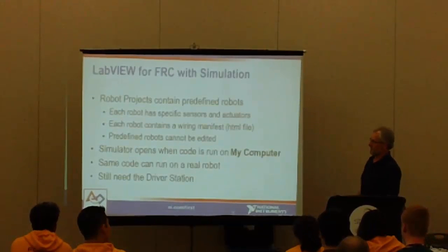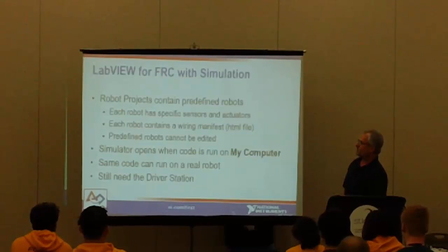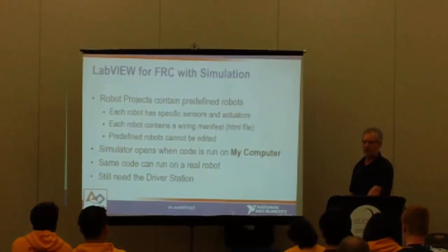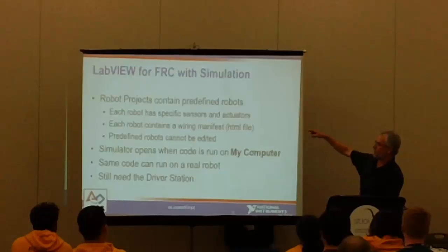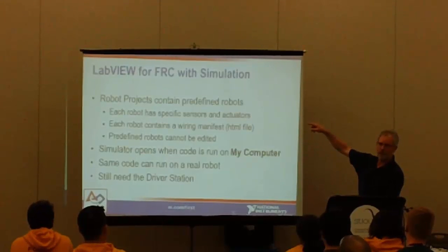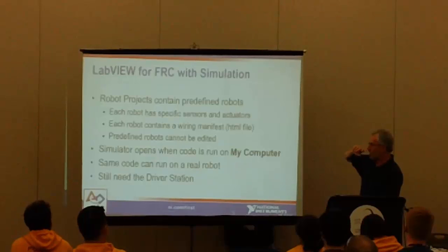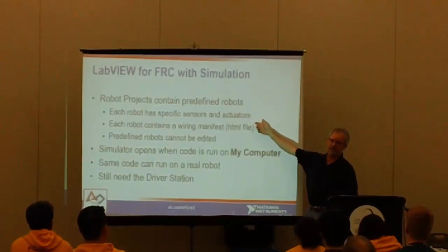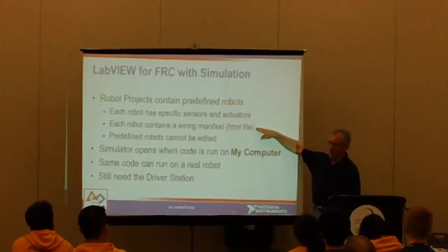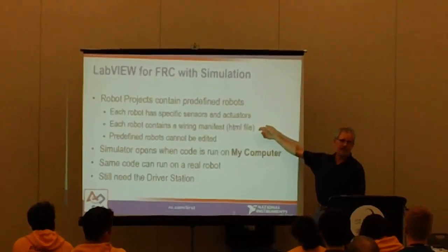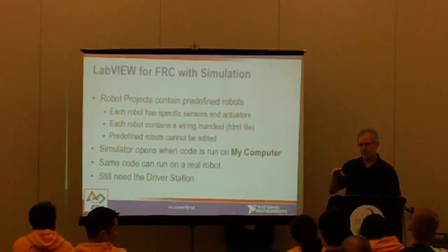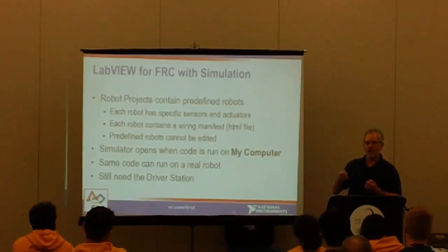So I mentioned simulation, and I want to bring this up. This is nice if you want to learn LabVIEW and you want to learn for FRC robotics, but not everyone has a controller or a whole setup for that. So what we have done is we have projects that contain predefined robots. We'll take a look at these in a minute. The robots all have specific sensors and actuators on them, and they also contain a wiring manifest. This is just a list of, for the inputs and outputs, like the motors and indicators, what they are wired to, what channels on the roboRIO.